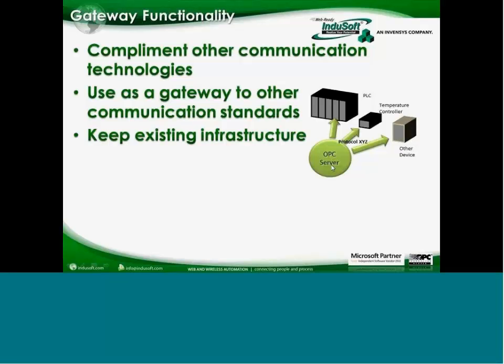So let's show you this. This is what I had on the other slide down in the bottom right-hand corner. This is the OPC server talking to various devices, and it could be any devices. It doesn't have to be PLCs. It could be temperature controllers, drives, building automation systems. There's a whole lot, and Tom will touch on the different types and quantities of devices in his presentation. So let's say that OPC server is communicating very happily to those devices. Now you'd bring in something like InduSoft Web Studio running on a PC or a Windows type environment, and using the OPC defined standard, we would communicate to that OPC server, where it in turn communicates to those other devices.